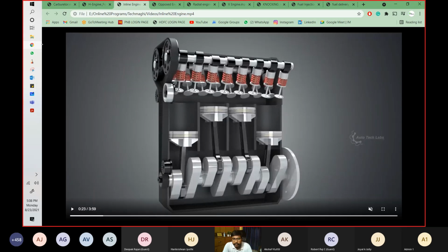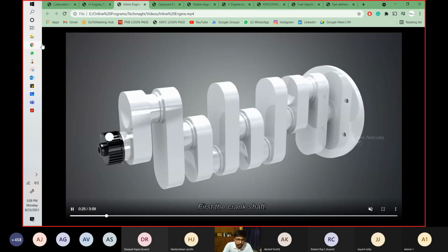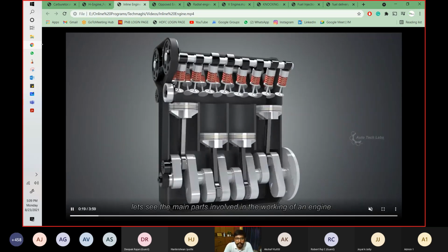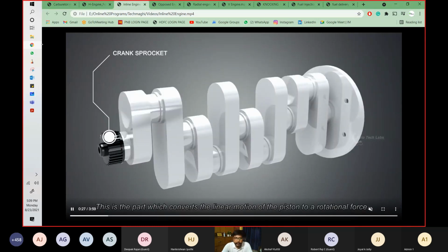You see when this camshaft is rotating, this is the rotation of the cam and follower. This is a mechanism. If you have ever heard or studied it in your engineering, then you must understand that a cam is designed for a specific operation: it operates anything for a particular duration, and for the rest of the time it closes itself. So you see, this is how rotation of a cam is operating any valve. And this is your crankshaft basically.